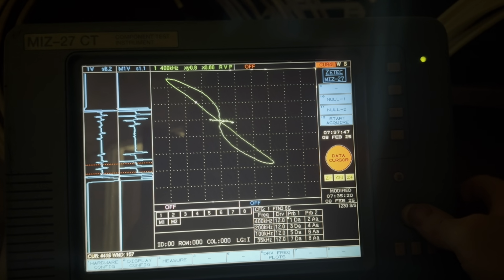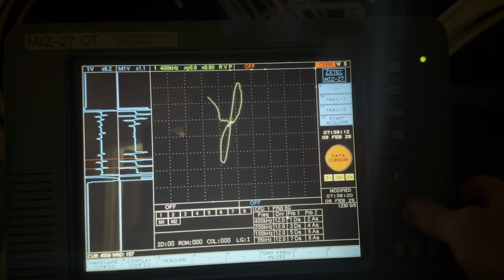So the 100%er looks the same on all of the channels. Channel 1, channel 3, channel 5, they're all set to 40 degrees. Now the reason they're all at 40 degrees is because I set them to 40 degrees, okay? That was done on purpose. But when I leave it set to 40 degrees on channel 1, 3, and 5, watch what happens when we pull the probe past the 60%er, which is a little bit farther away before the eddy currents see anything happening.